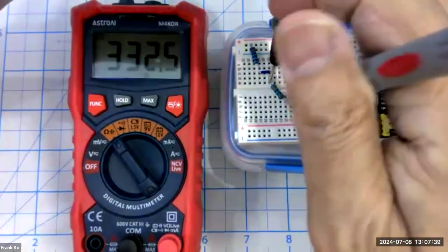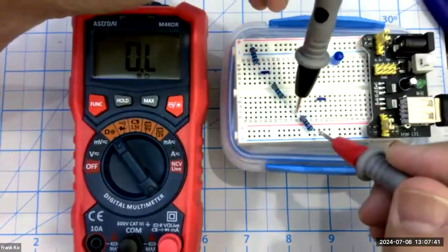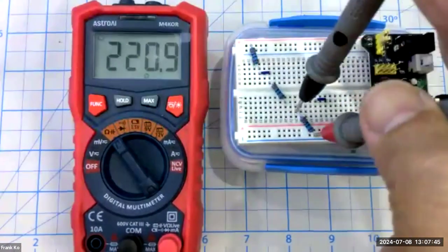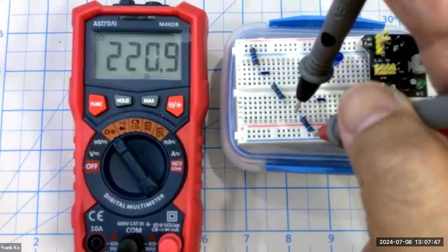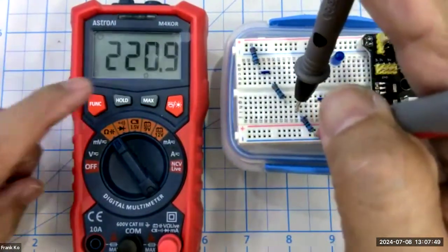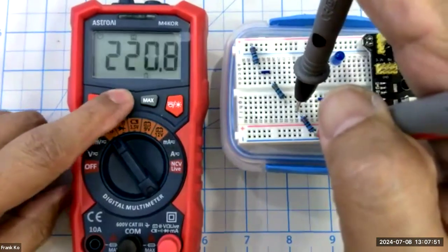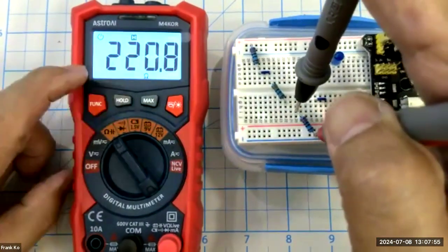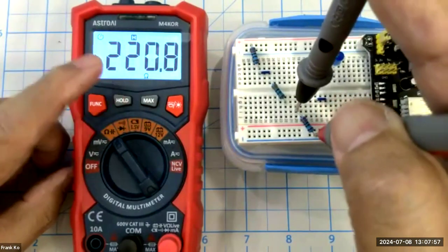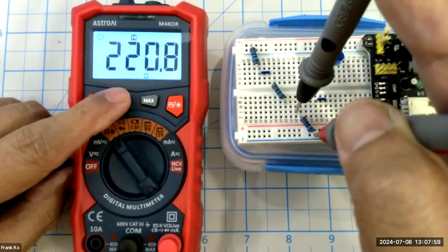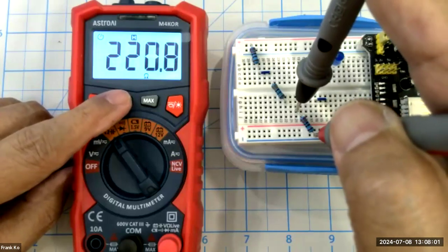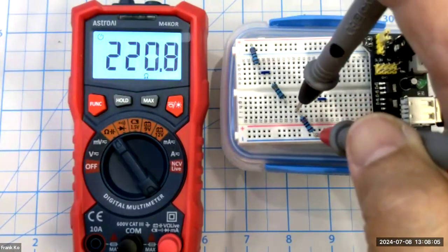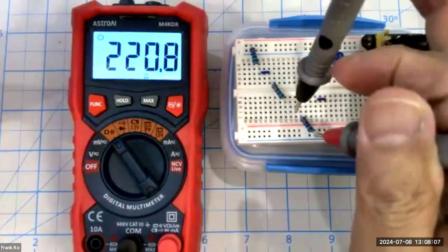All right, last resistor should be a 220. We want to measure that this is a 220 and confirm, hold steady, 220.9. If it's jittery, it changes, we should illuminate to see things a little more clearly. You can press hold if these numbers are dancing around. They generally won't for resistance if you've got the probes on nice and steady. So we don't need the hold here as much as we did for the other kinds of measurements.